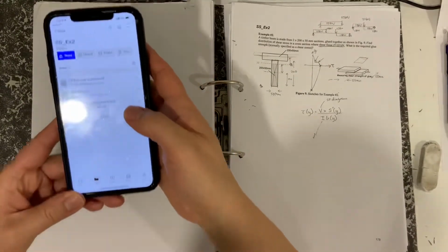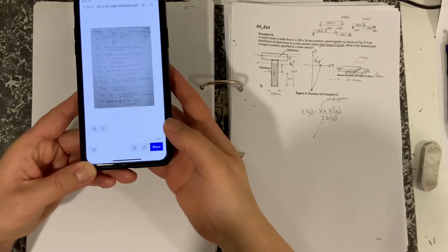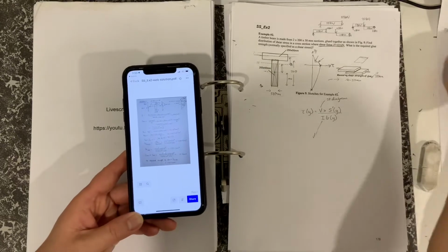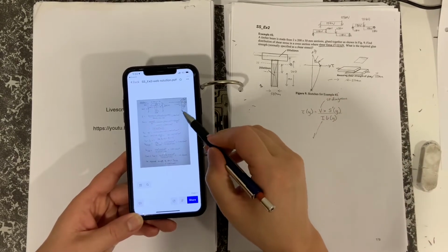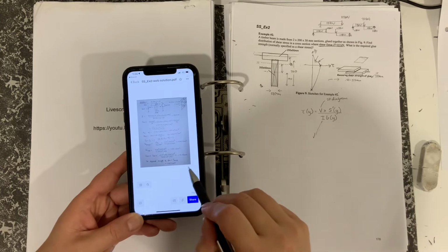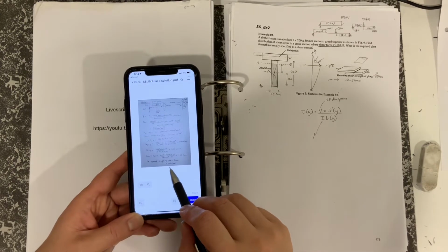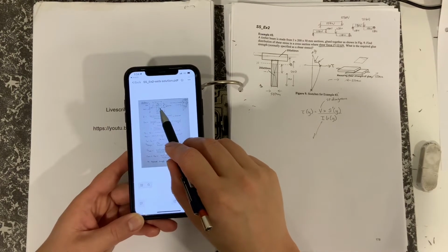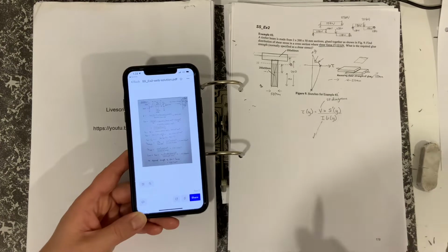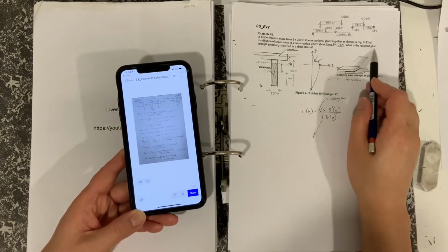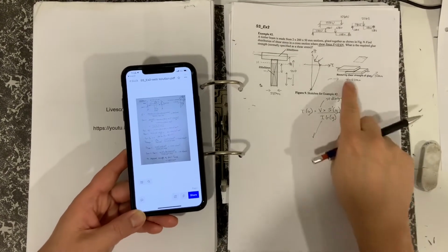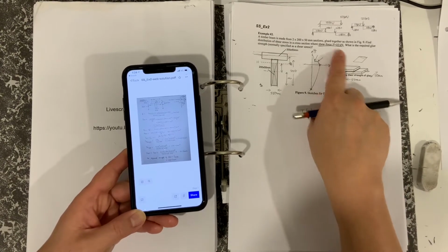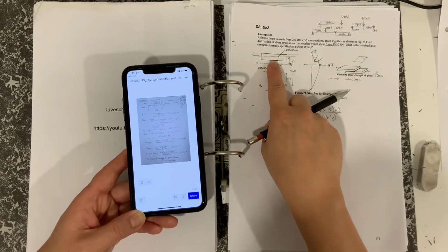So if you look here on the Dropbox, you can see that's pretty much what we've just described, and the calculation to work out the distribution of the shear, and also the required glue strength in terms of tau that would need to be there under that shear force in order to keep the section together.